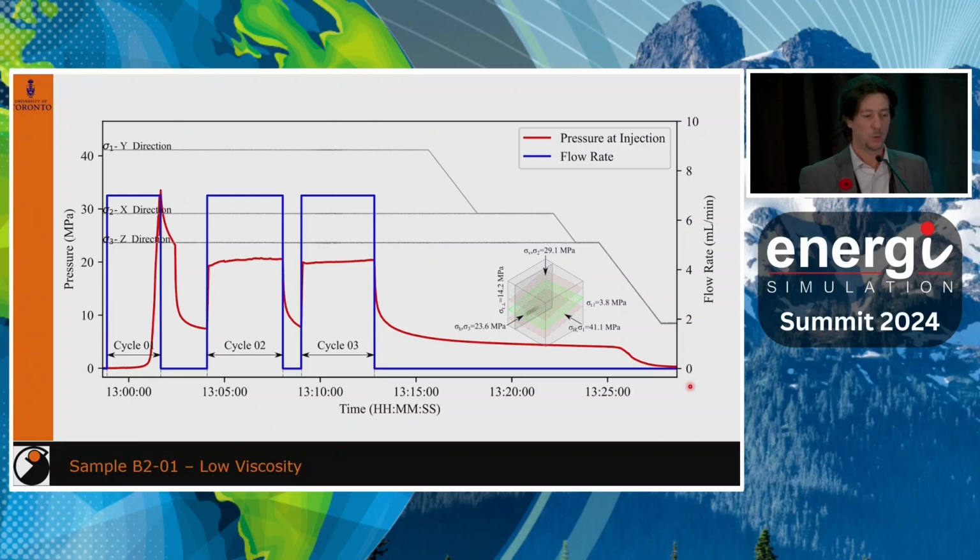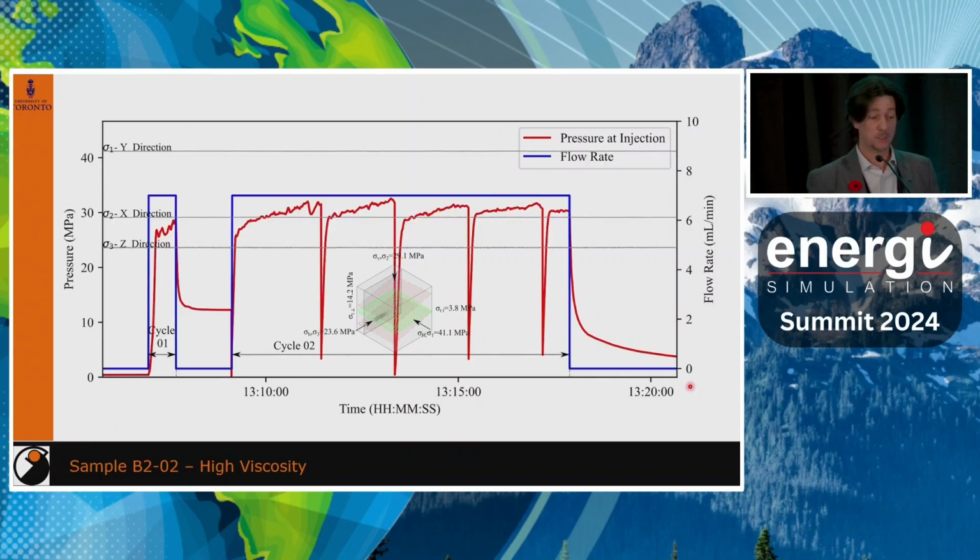But what we did during that particular study, we were asked to change the fluid. We used a low viscosity fluid, and we looked at how the fracture was propagating, and specifically, the sponsor was interested in the breakdown pressure. And we wanted to compare the breakdown pressure with a high viscosity surfactant.